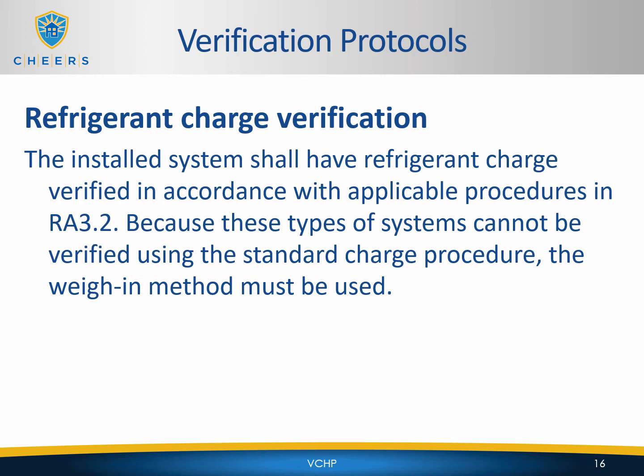Refrigerant charge verification. The installed system shall have refrigerant charge verified in accordance with applicable procedures in RA 3.2. Because these types of systems cannot be verified using the standard charge procedure, the weigh-in method must be used. So these are the same requirements that you follow for any standard refrigerant charge verification. There's nothing special here in regards to this being for the VCHP verification.